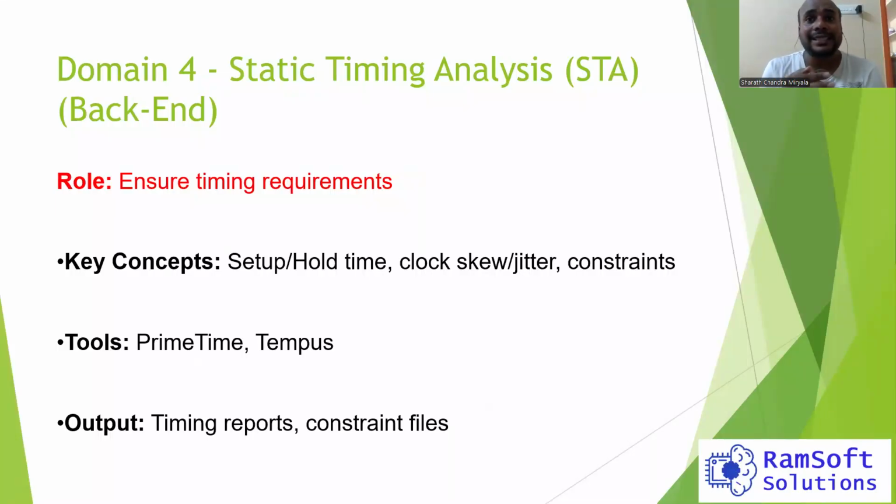What STA does is ensure the signals in the design will reach their destinations on time. Our duty here is to verify the setup time and the hold time. If there are any violations, you need to address them.